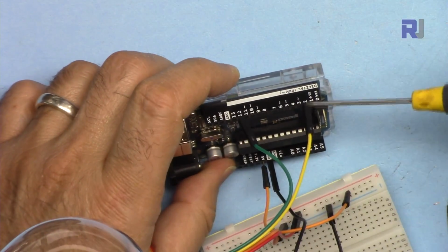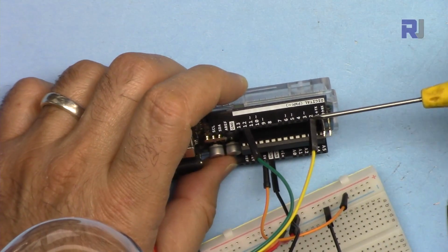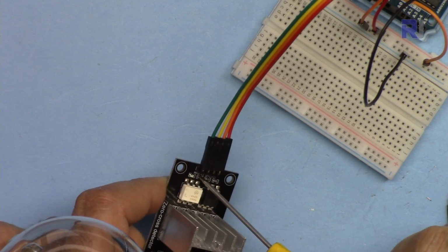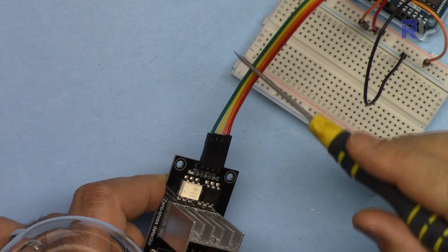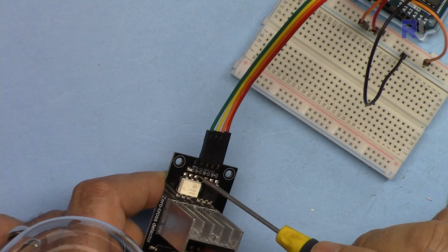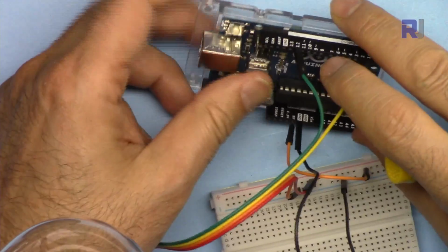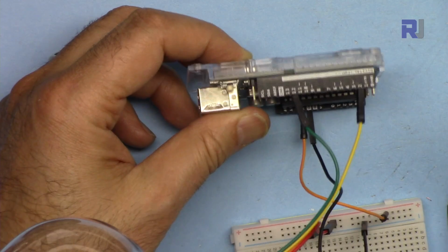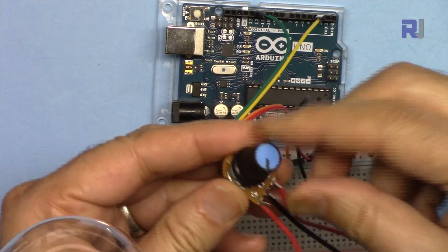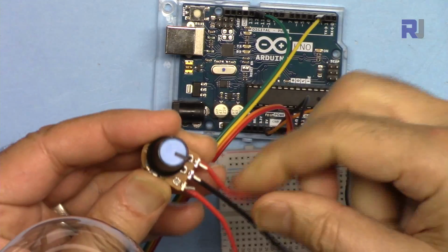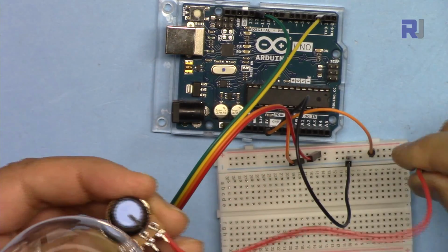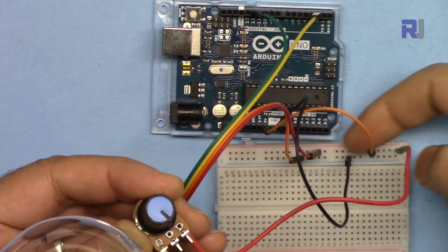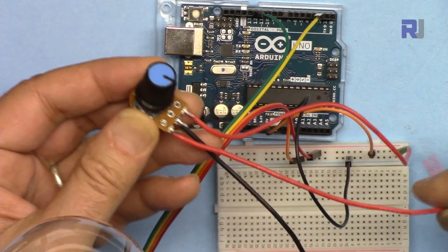This is an interrupt enable pin or interrupt pin. You cannot change it, it must be connected here. And the green is the last one, which is the pulse width modulation or the signal pin. This is a signal that is coming here, and we have used pin 12 here. You can change it to some other pin if you wish. For my potentiometer, because I want the right side to be maximum, I will use this wire for 5 volts, connecting it to any pin on that red side, and the left one is connected to the ground.